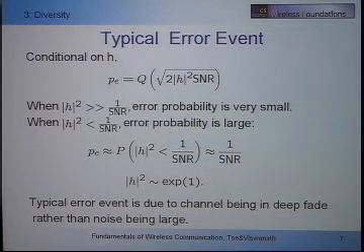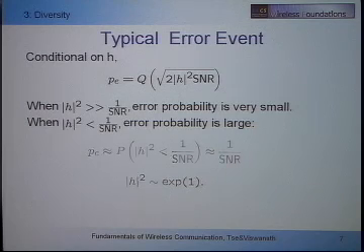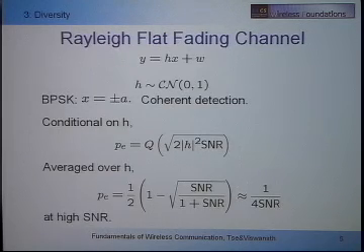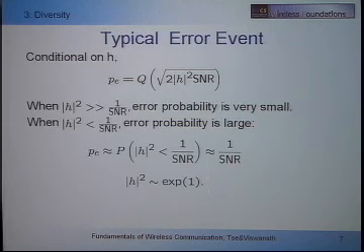So now, what have we accomplished here? Well, you may ask me, geez, I already have an explicit formula for the error probability. I actually did a Taylor series expansion to get this formula. Very exact, very nice. Why am I doing this over again? And instead get a wrong answer? What's the point of doing that? The point of doing that is, although I get a wrong answer, I don't get exactly 1 over 4 SNR, I get the right dependency on SNR. And that's the most important thing, because SNR is a design parameter. So you want to know how your performance depends on the design parameter.